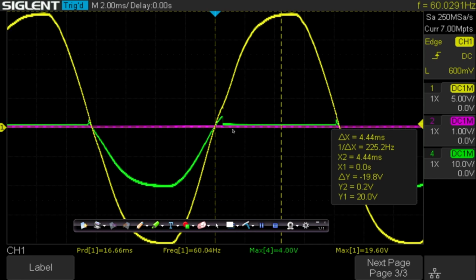I've used my horizontal control to align the start of the positive half cycle right on the center line of the scope. You can put it wherever you want, but with that adjusted to the minimum firing angle, you notice that it doesn't go quite to zero, and the reason is you can't trigger the SCR at 0 degrees because it needs a little bit of current to switch it into conduction.